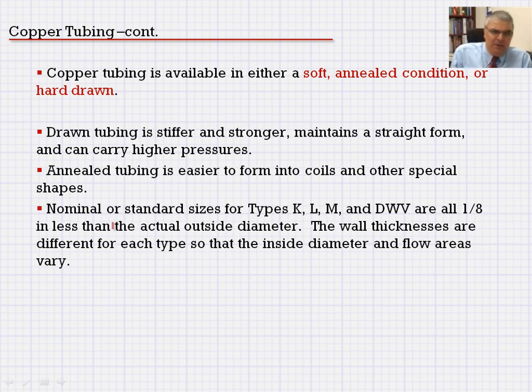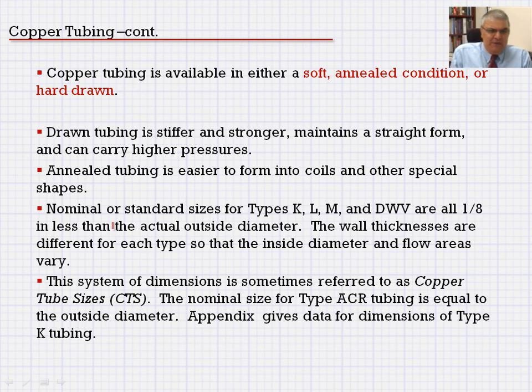The nominal or standard sizes for different types, K, L, M, DWV, are all 1/8 of an inch less than the actual outside diameter.